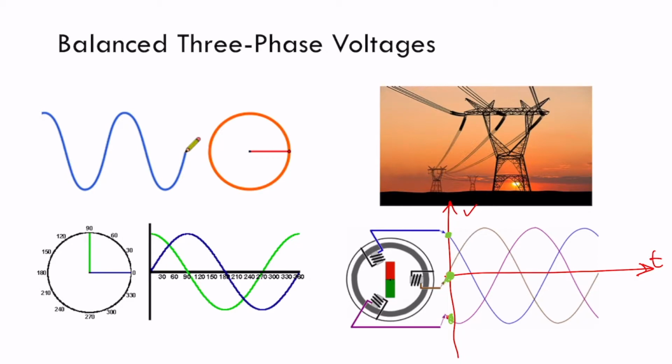If we go to any other position, we will see also that there are these three elements. The voltage of one will be 0 at this moment, and the value of this one will be cancelled out with this one. So if we create three signals in such a way that they are shifted 120 degrees, the sum of all of them at every moment is 0. And this actually has a very important